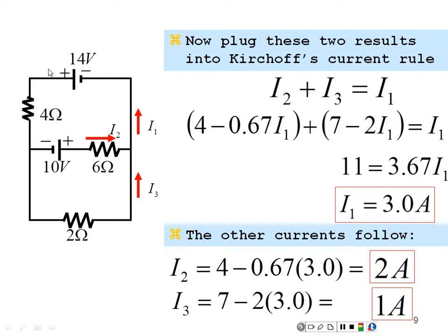Or I could go plus 4I1 plus 2I3 gets me there as well. That would be 4 times 3, which is 12 volts, plus 2 times I3, which is 2 volts, 14 volts. It doesn't matter how you go from A to B. If you add the voltages between those points, you get the potential difference between those 2 points using this method.